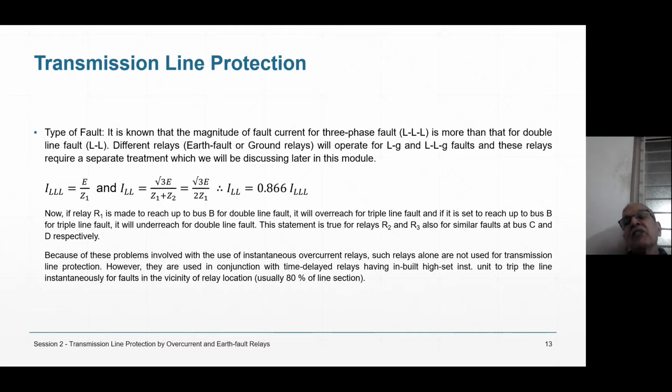That is the biggest disadvantage. That is a very great disadvantage of the instantaneous overcurrent relay. Also, when the fault occurs, the generators go out of step, but generators can remain in asynchronous conditions for a few cycles: 8 cycles, 10 cycles, 12 cycles.